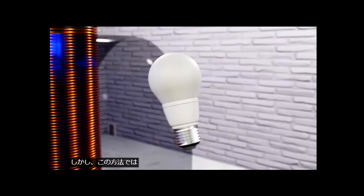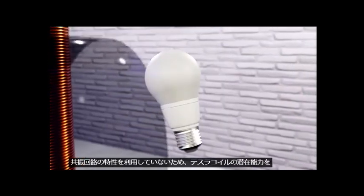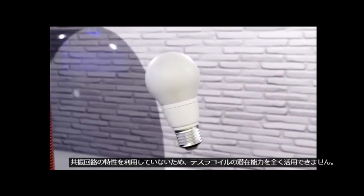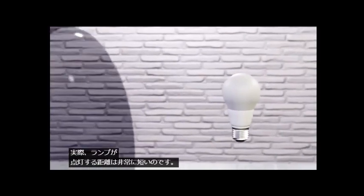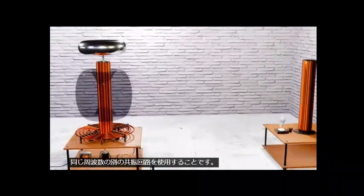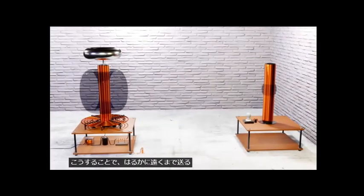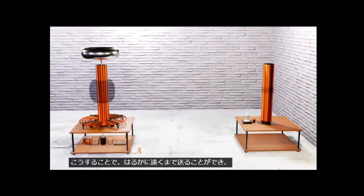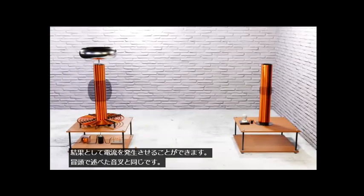But this way we will not take advantage of the potential of the Tesla coil at all, since we are not using its resonant circuit quality. In fact, the distance at which the lamp will light is quite short. The true way to use a Tesla coil to transmit power wirelessly is using another resonant circuit with the same frequency. In this way we can be much further and still generate an electric current as a result, just like the tuning fork we mentioned at the beginning.